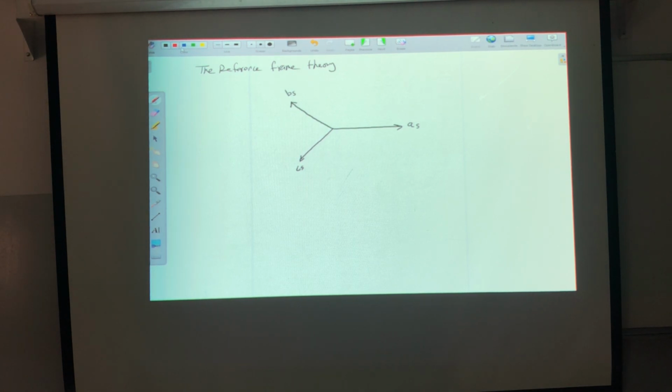In the machine, Dr. Sahar told you what? We need to give it voltage, and there was a capacitor to make the split phase. Split phase means that you are artificially making another phase, imposing another phase. They recommend adding a capacitor in order to make the angle as wide as possible. The maximum is 90. By the way, if you just rotate it, it rotates.